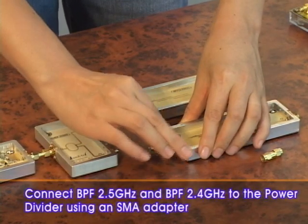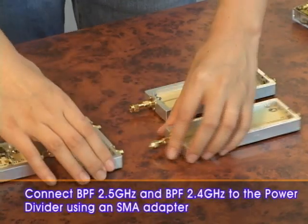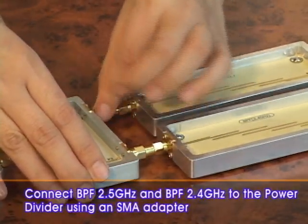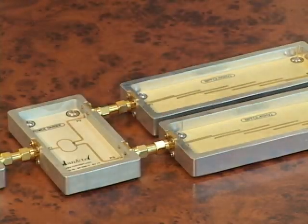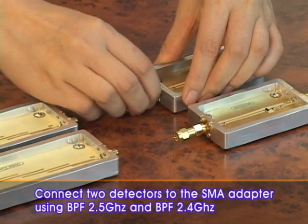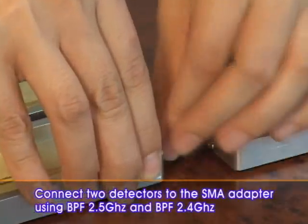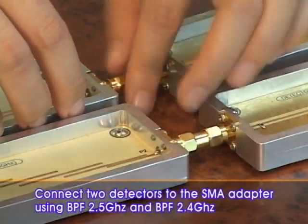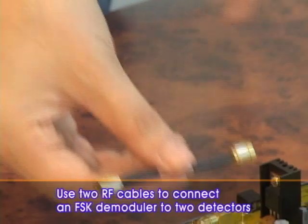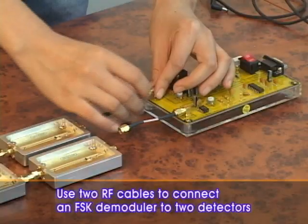Connect the BPF 2.5 GHz and BPF 2.4 GHz to the power divider using an SMA adapter. Connect two detectors to the SMA adapter using the BPF 2.5 GHz and BPF 2.4 GHz. Use two RF cables to connect the FSK Demodulator to the two detectors.